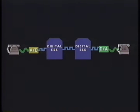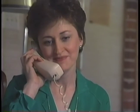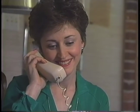Since the 1980s, however, digital switching has been possible at the central office. When it enters the switch, an analog signal on a phone line can now be converted into a digital signal at the originating office. It then remains digital throughout transmission until it reaches the terminating office. Digital lines can be directly switched at the central office. No conversion is necessary. Because the number of conversions is minimal, digital switching provides improved sound quality.